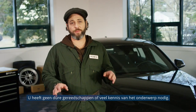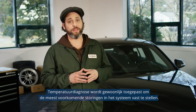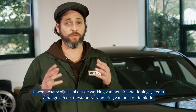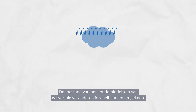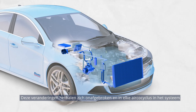Now, you don't need any expensive tools or have to have a lot of knowledge on the topic. It's not rocket science. Temperature diagnostics is commonly used to determine the most typical failures within the system. Now, you probably already know that the operation of the air conditioning system depends on a cyclic change of the refrigerant state. The refrigerant can change its state from a gaseous state to a liquid form and the other way around. And these changes happen when the air pressure and the temperatures change inside of the loop. And these changes repeat continuously within every AC cycle in your system.